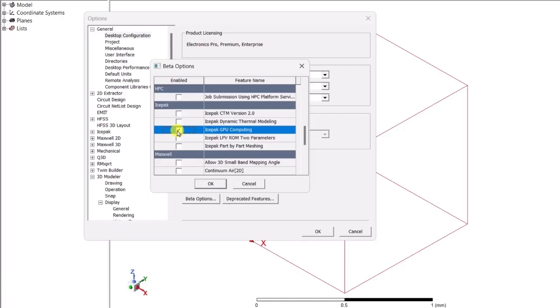A warning message that includes the unsupported features is reported in the message window. Icepak designs containing the following objects or settings are automatically run using the CPU. Transient solution type, PCB component, PCB networks, internal fans, network boundary condition, no reverse flow option, shell conduction, joule heating, all turbulent settings except realizable 2 equation and K omega SST, ray tracing radiation, solar loading, solve flow and energy